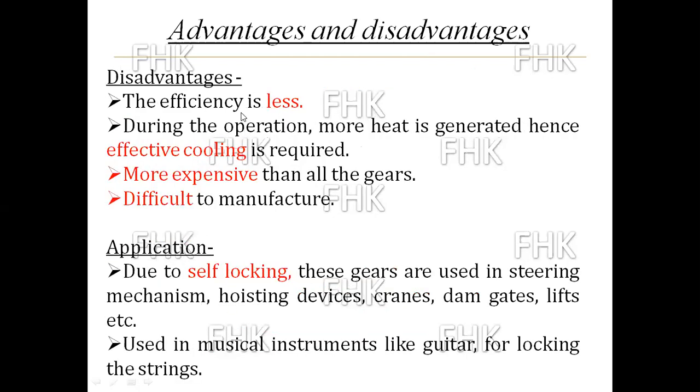The disadvantage of this gear drive is that the efficiency is very low as compared to other drives. During the operation, more heat is generated, hence effective cooling is required. For that purpose, this gear drive is always placed deep in oil. Third, these are more expensive than all the gears, as they are difficult to manufacture. As the manufacturing of worm and worm gear drive is difficult, it directly affects the cost, so it is more expensive.